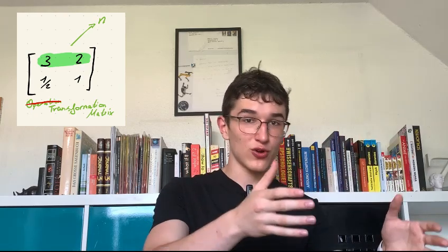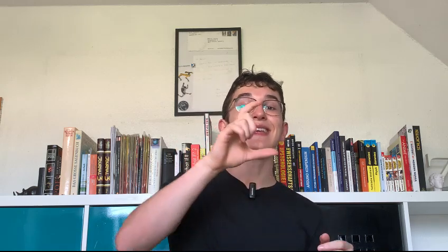And to be honest, I've kind of been lying, since the matrix with the operations inside is called a transformation matrix, because it transforms numbers, vectors, coordinate points, or angles, and that's basically the basis of Denavit-Hartenberg parameters. If you do forward kinematics, it's going to take angles and transform them until you find out what the n coordinate is. And if you do inverse kinematics, it's going to take the coordinate points and transform them until you have the angles for each joint. That's why you have to make a transformation matrix for each joint if you're using the Denavit-Hartenberg parameters.